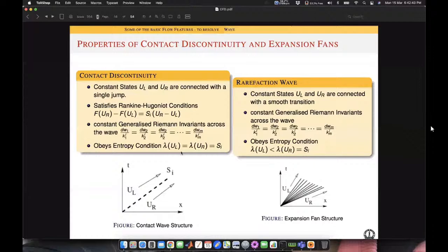And if you draw a thin line over there, and assume that everything is moving uniformly, you see that to the left of the line the density of the vehicles is high, and to the right of the line there is basically no density at all. Of course, one or two vehicles you can assume. Okay, so that's called a shock wave. So the shock wave is moving in that direction.